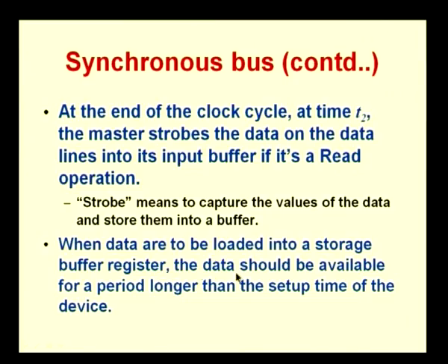Okay. So, when data is to be loaded into a storage buffer register, the data should be available for a period which is longer than the setup time of the device. So, since I have to store it into the buffer, remember whenever we store into any buffer, which is essentially any memory component, there is something called a setup time and a hold time. So, you need to therefore make data available before the setup time, and you need to hold the data for a little time which is more than the hold time. Okay. So, both these have to be taken into account when you are deciding on the clock pulse width.